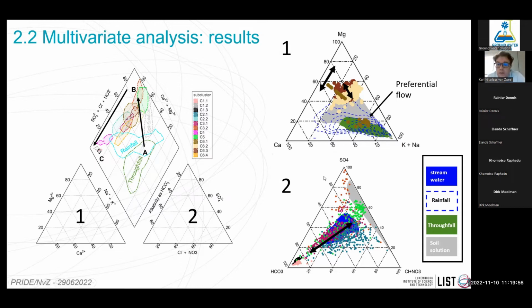So, but then the two shallow clusters, this is what is interesting that we observed, and we also observed this in a stream, but we could not explain the difference between the two. They have more or less the same variance in terms of calcium and magnesium, but a distinct difference in terms of sodium concentration compared to calcium and magnesium. And this is solely because of ion exchange.